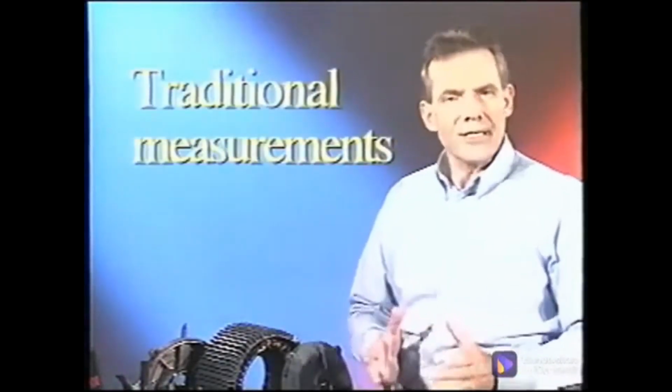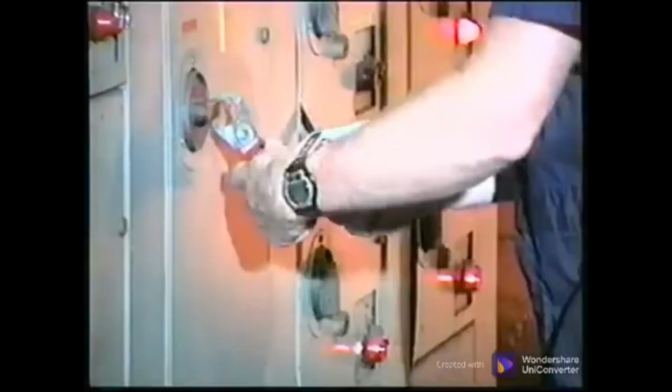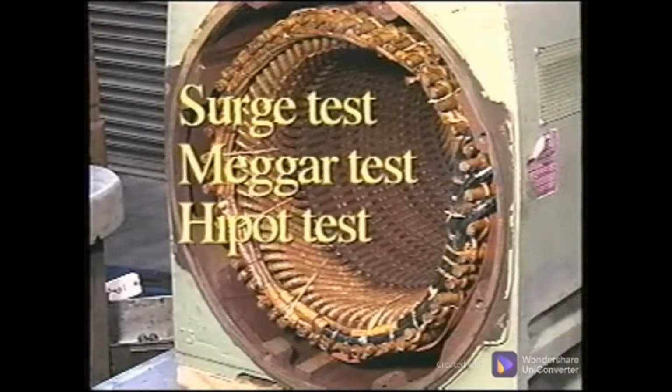Let's take a look at traditional measurements used to detect some of these problems. Traditional tests require that the motor be taken offline and the power supply lines be disconnected from the motor, and these tests can only detect stator problems. 3 tests are commonly used. They are a surge test, a Megger test, and a high-pot test.